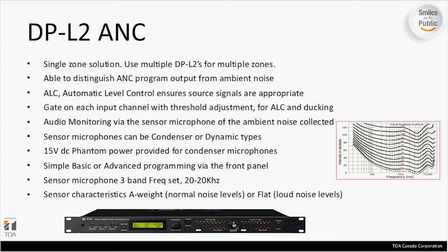We can set gating and threshold adjustment. For example, if you're doing paging and you have background music in the environment, you'd want to duck the background music down so that the paging would be clear and concise and would be able to be heard and understood. We also have an output for audio monitoring, so you can actually listen to or record the ambient noise that is collected by the sensor microphones.